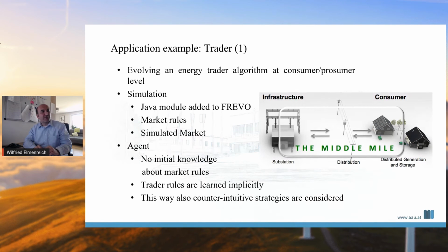And it wouldn't make a difference if you run the device right now or later in the evening or during the night, unless you have a tariff that is based on different working hours, and it definitely changes when you are having a local photovoltaic system installed. Because with your local photovoltaic system, you are mostly interested in using the power from the photovoltaic system within your system and not feeding it back. And the device also should rather use the photovoltaic generated power than buying power from the grid. Because the worst case would be photovoltaic system during noon is feeding in all its power, while the devices are then later buying energy back from the grid.